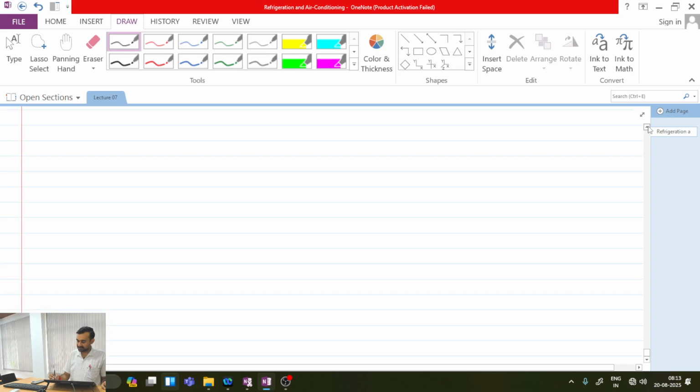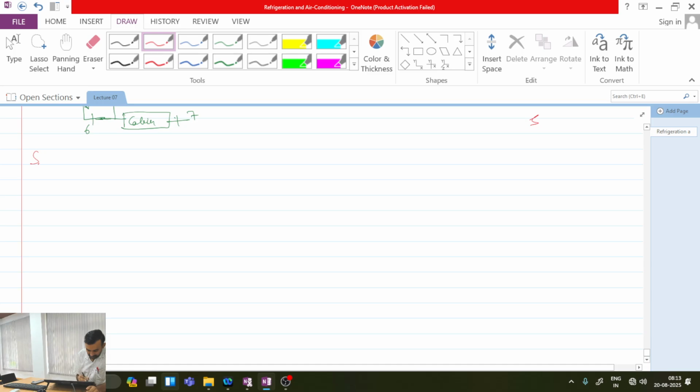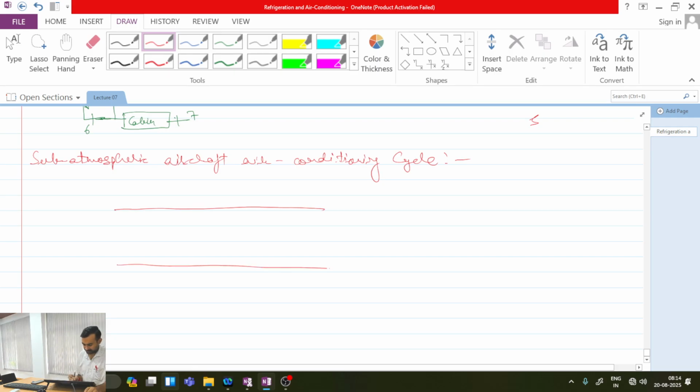Now one more cycle is left. What is that cycle? Please tell me. Subatmospheric aircraft air conditioning. What we do in this cycle, again a simple variant, is that here we use basically two turbines, multi-stage expansion. Okay, how we do that, let me explain.